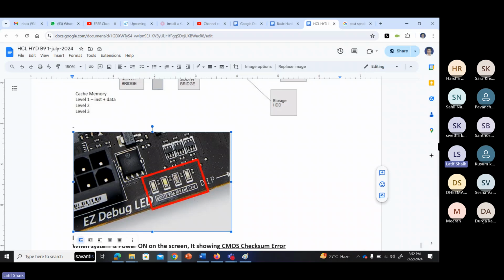When I assembled a desktop for myself, usually in Corona time, after 6 months we got some relaxation, so I ordered individual parts and assembled them. I made small mistakes, then assembled everything and turned on my desktop. It showed the VGA LED blinking. So I started searching and finally found my processor, an i3, does not contain any graphical memory.